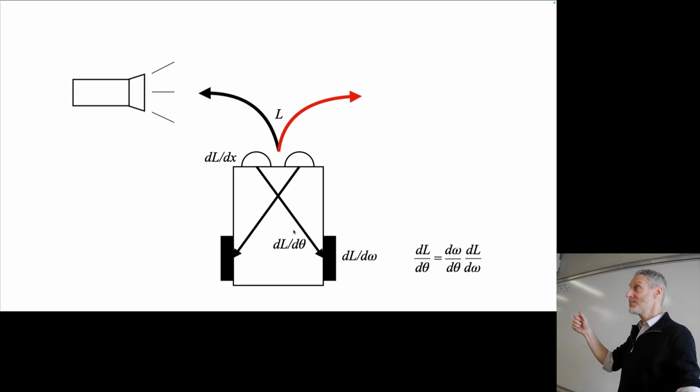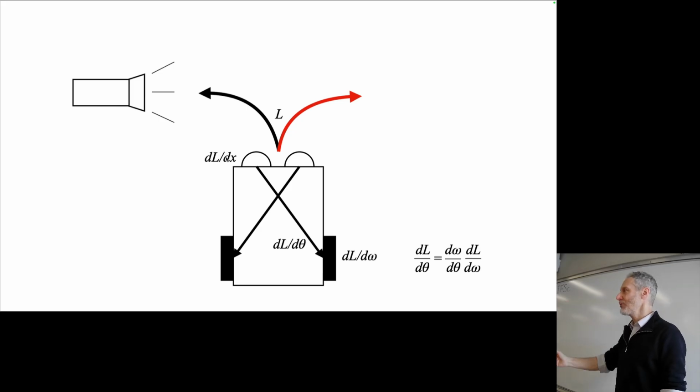If theta is bigger, that also reduces L. And if x is further to the left, the sensor is further to the left, that also brings down L. We're able to, in our heads, figure out all these local gradients. Luckily, that's what the differentiable simulator does for us. You can imagine where all this is going. The minute the robot gets more complicated and we have a more complicated fitness function, forget about it. You can't figure out these local gradients.